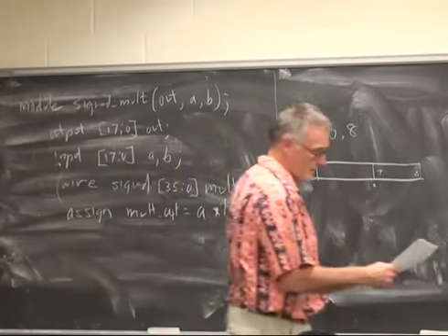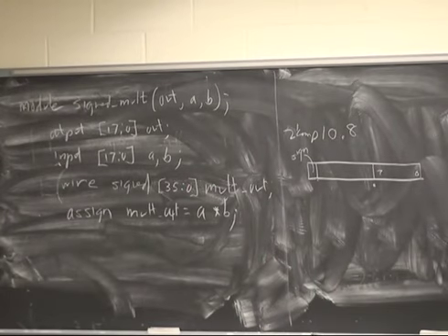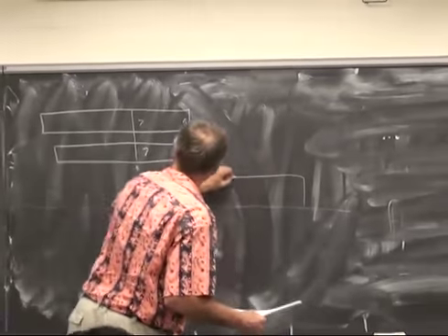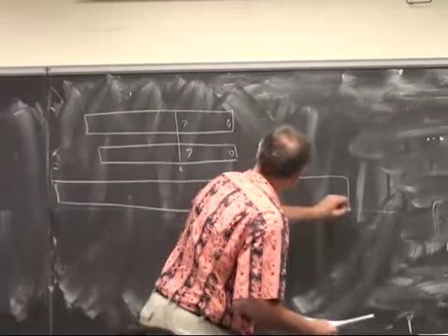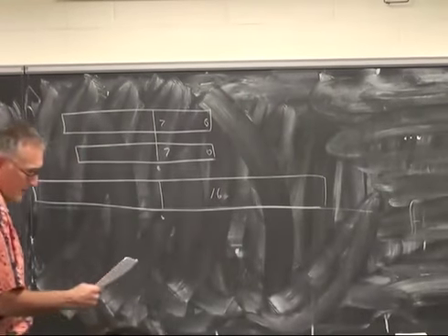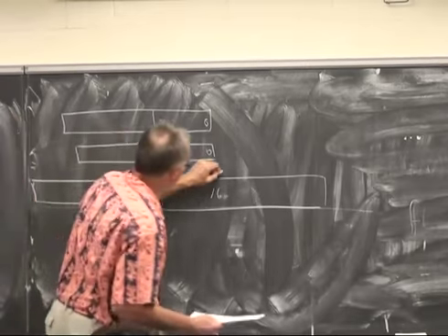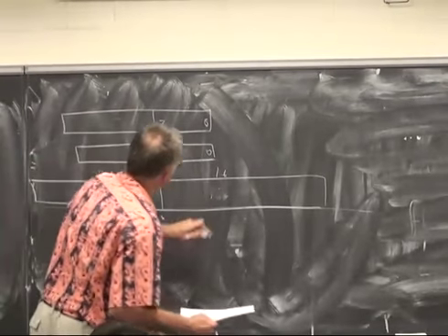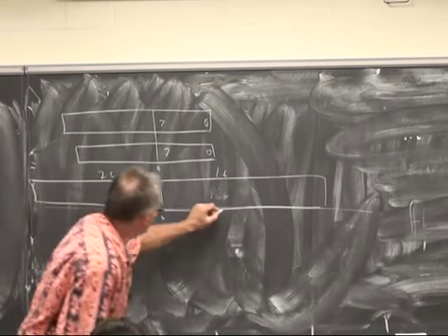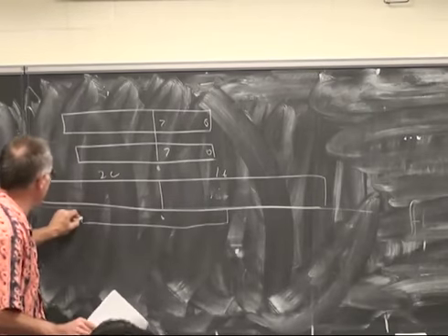So the next step here is to say that if we have two 18-bit numbers that are in 10/8 format, then the output of this multiply is in 16/20 format, and what we have to choose as the output are the sum of the bits.